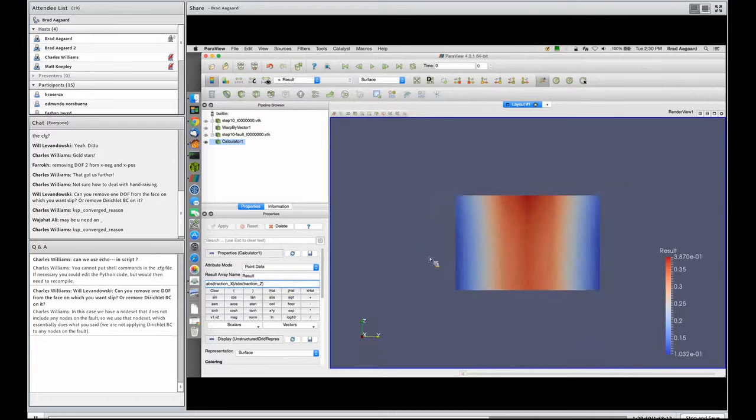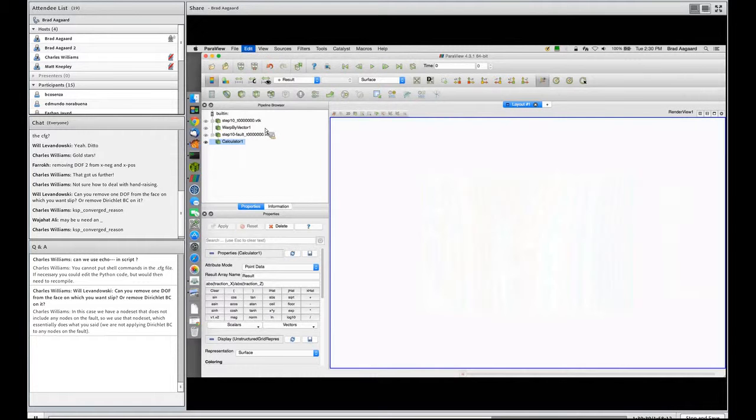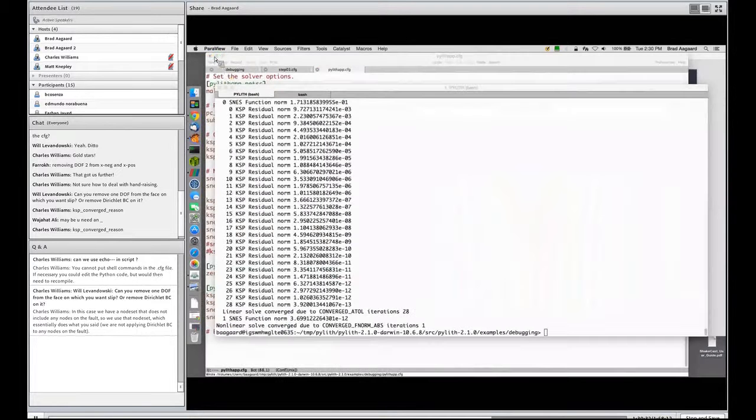So what we see here is the result is our shear divided by our normal traction is varying from 0.38 down to 0.10. 0.10 at the ends where we have a free surface boundary, where our normal stresses are less. And 0.38 in the middle. We said our coefficient of friction was 0.6 when we set up the problem. So we don't have enough shear to create slip. So in this case, we're going to increase our displacement.